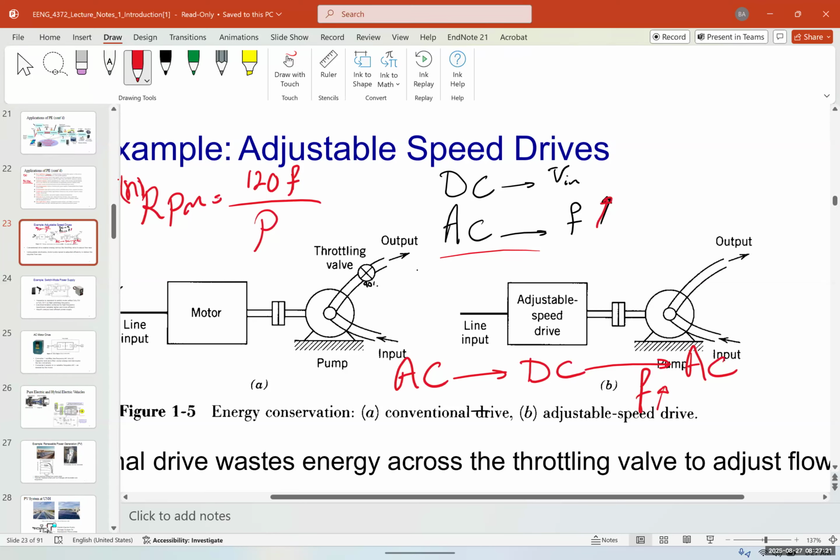very, very precisely. Say, for example, let's do this exercise, and the RPM is the same for the motor as well. Imagine this has 8 poles or 6 poles. Let's say it has 4 poles. So P is 4. And I wanted to run at, let's say, 6,000 RPM.